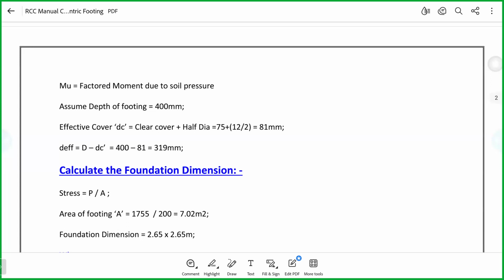When placing a foundation, they place PCC and also one plastic cover. The plastic cover will be right below. The plastic cover will be first on top of soil. Then they'll go for PCC. So one question: why shouldn't the concrete and soil be mixed? See, if you mix concrete and soil, it will affect the main reinforcement. Okay, the footing. Then what will happen?